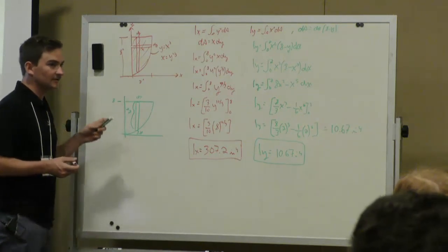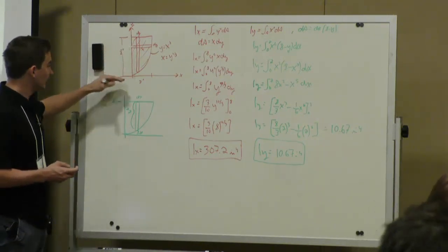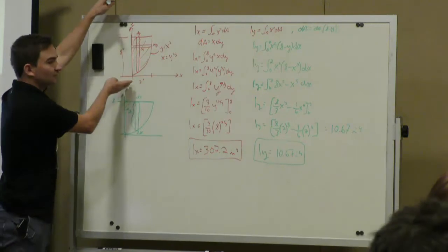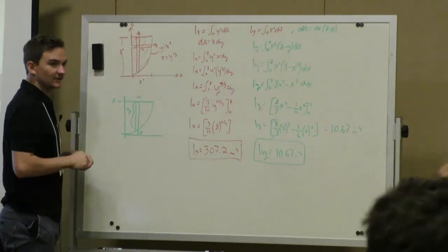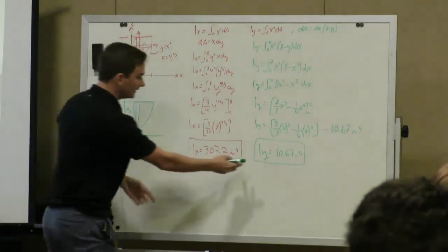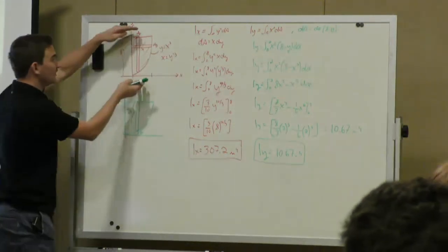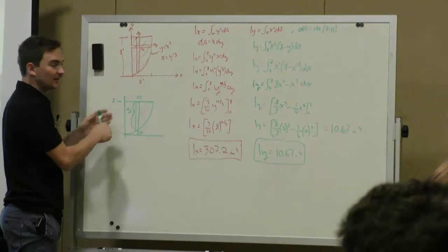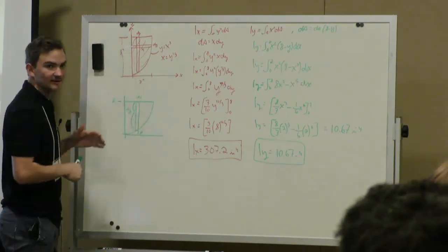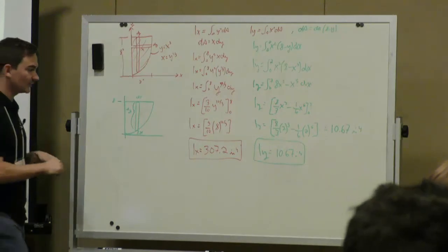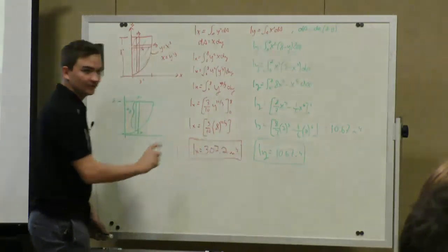Yeah, very good. So did everyone hear that? From the x-axis, the area stretches much farther than from the y-axis. So that's one way to double check if your numbers seem right. Ix should be much larger than Iy, because from the x-axis it only goes out 2 inches, whereas from the y-axis it goes up 8. So that's just a way to double check between the two values.